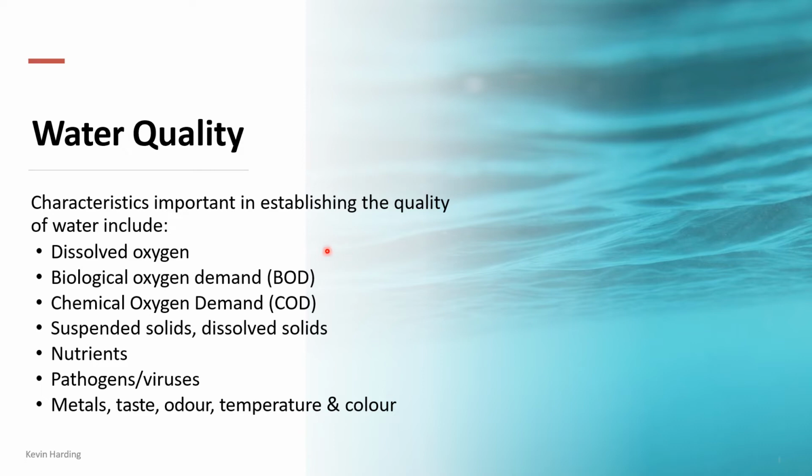For this course, I'm only going to ask you, and you only need to worry about the biological oxygen demand when it comes to actually calculating numbers. So in this week's TUT and the examples that we'll briefly just skip over later in the slides, please make sure that you can calculate the biological oxygen demand for a wastewater stream.